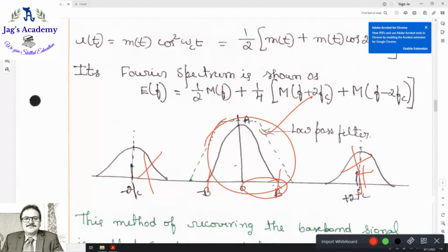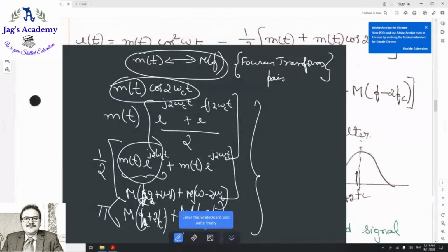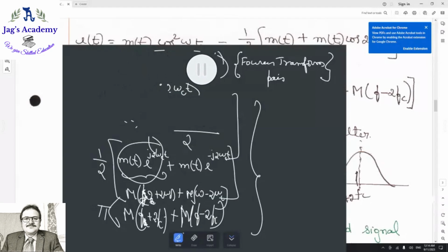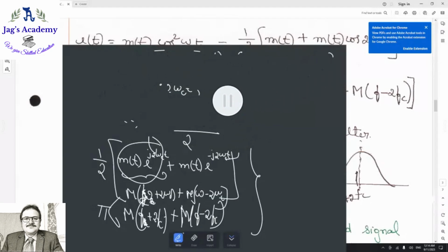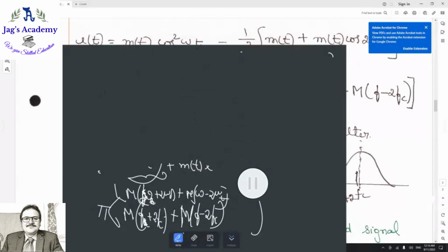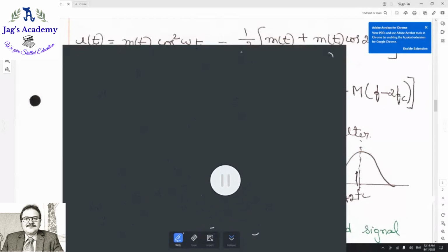Now can you tell me what is this? Is it not the spectrum of the original signal? You got it back. After modulating, you got back your original signal. That's what demodulation is. See, demodulation in double sideband suppressed carrier wave is very easy, right? It's a very simple process, yes or no? Demodulation in double sideband suppressed carrier wave is very easy. Even generation is also very easy, right? How do both the modulator and demodulator look for double sideband suppressed carrier wave? Simply multiplication, that's all. And the entire theory behind it we have just seen now.